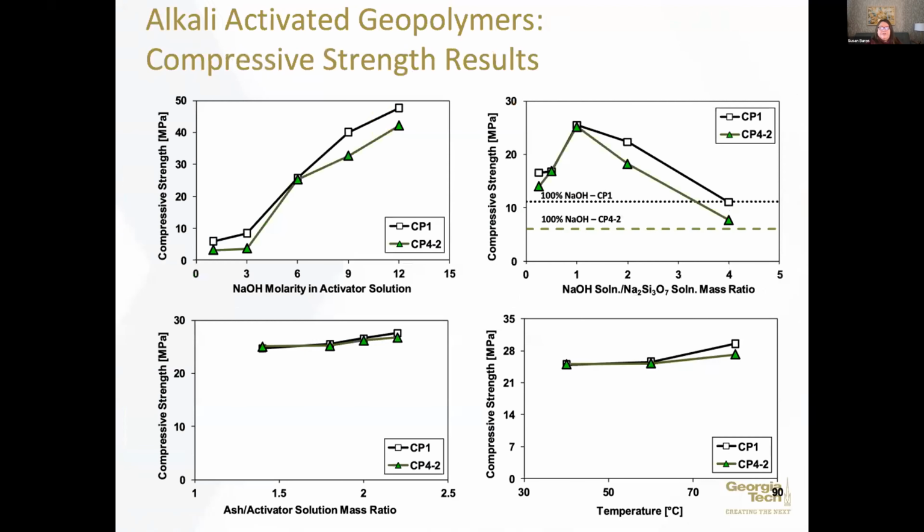So what does this mean for us, right? At the end of the day, we're worried about compressive strength. Can we make these materials strong enough to perform as we need them to perform as a construction material? And what we did was, if you see the points circled in red, those are our reference tests. And you can see that we ran an experimental matrix where we tested the effect of the sodium hydroxide in the activator solution. Okay, so in the upper left-hand corner here, at 6, we're looking at a compressive strength on the order of about 25 megapascals.